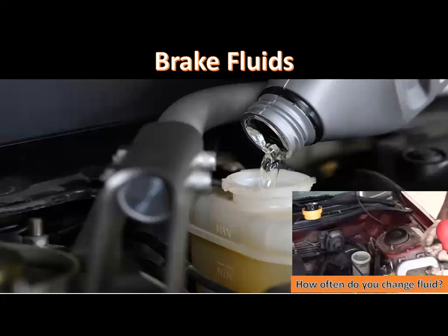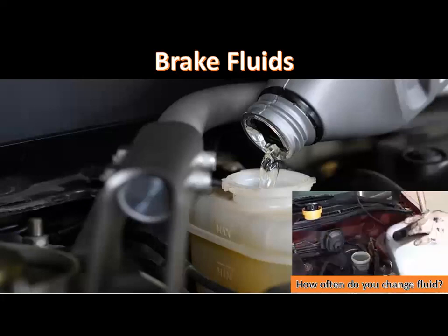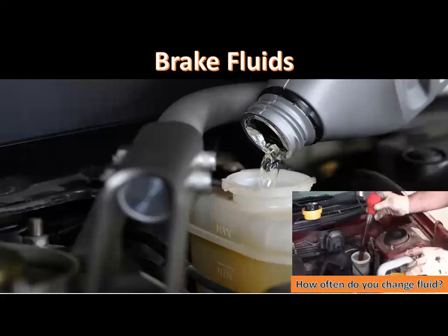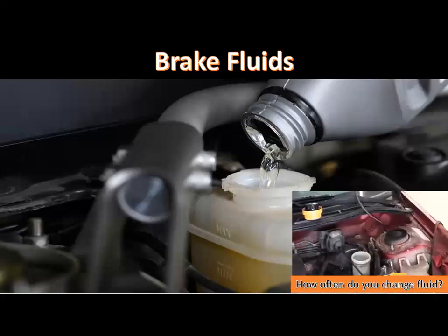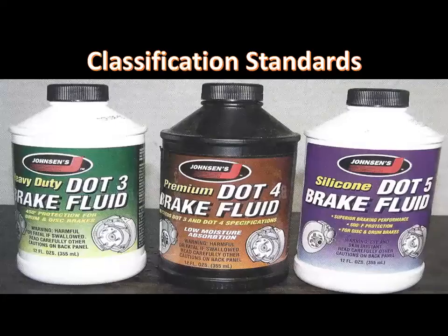Resistance to evaporation. Brake fluid must resist evaporation at high temperatures. Anti-rust and anti-corrosion. Brake fluid must combat rust and corrosion in brake system components. The DOT designates that brake fluid must meet classification standards established by the SAE, or the Society of Automotive Engineers.